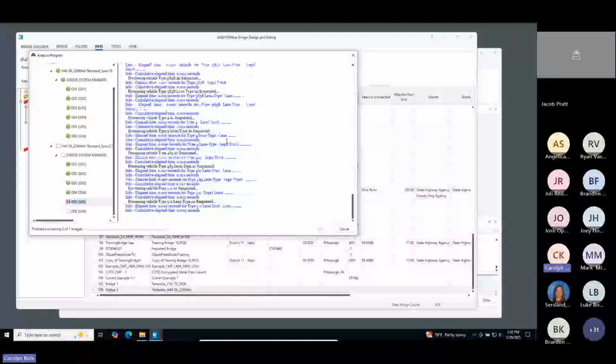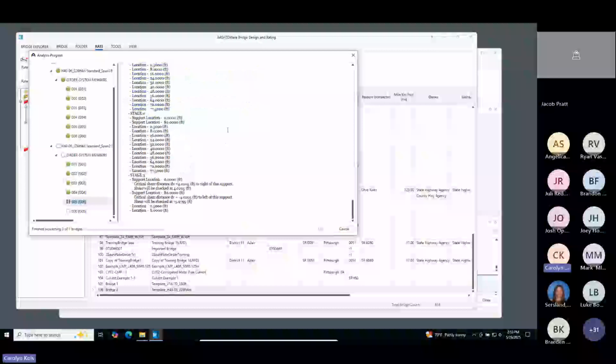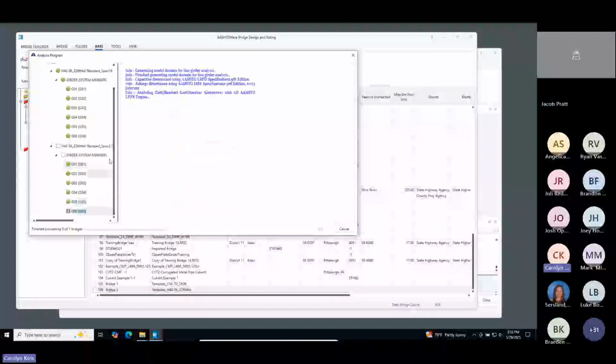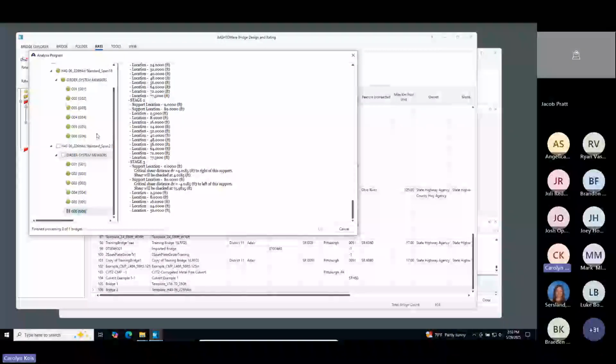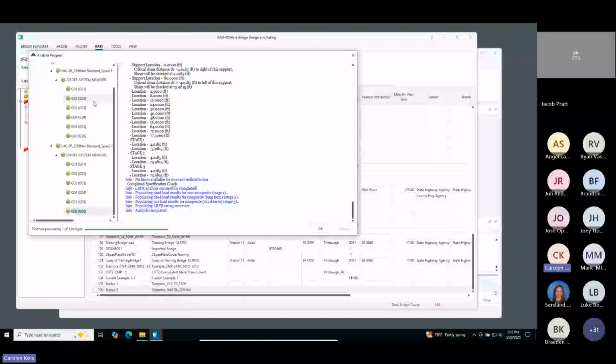Yeah, and this also comes back to highlight what we've been talking about with bridge alternatives. Here we can see that it's including the end spans and all the middle span girders. And like Mark said, if you had different component types within a bridge, or a separate approach span and main span, all of that will be included here as long as it's saved to a bridge alternative.